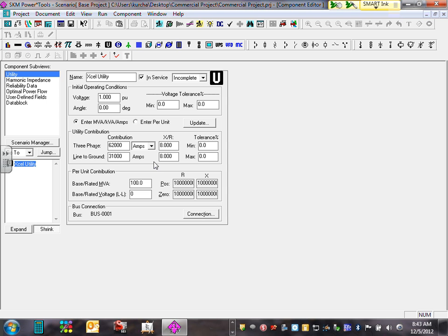These two numbers are sacred numbers. You get them from Excel or you calculate them like I did. No rocket science. First, you find the full load current of a transformer, then divide it by the impedance. You guys have done that, and you did the homework for me on that too. I came up with 50,000, based on that impedance. Anybody else come up with 50,000?